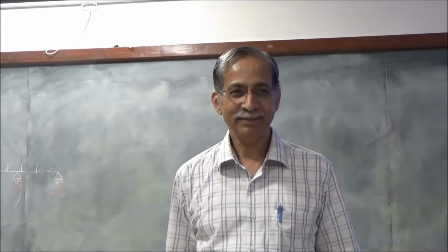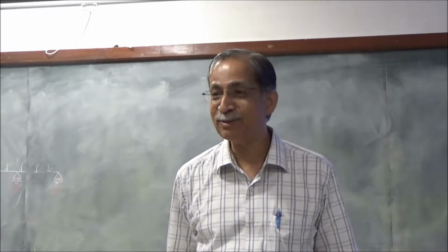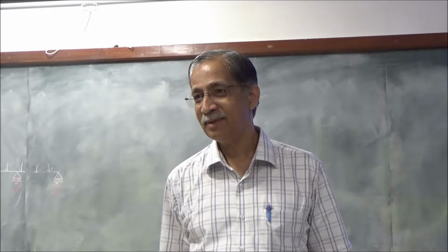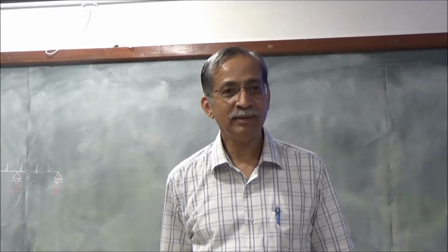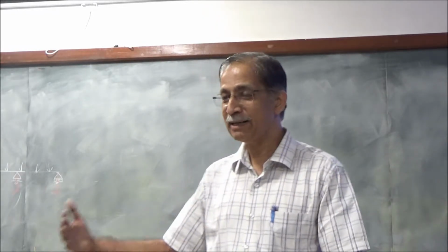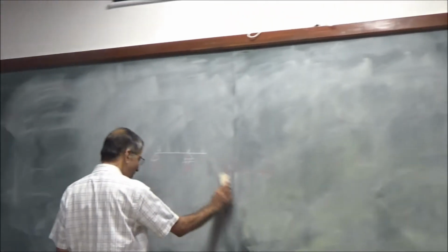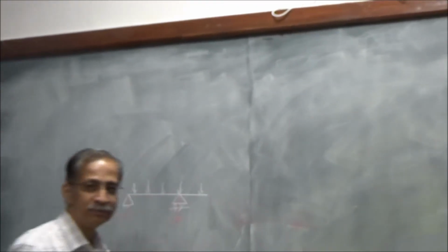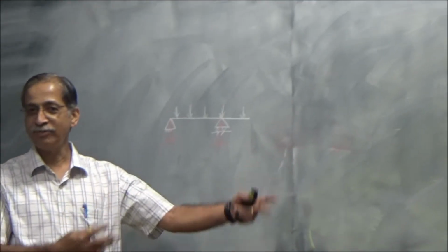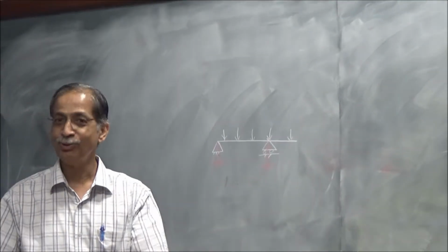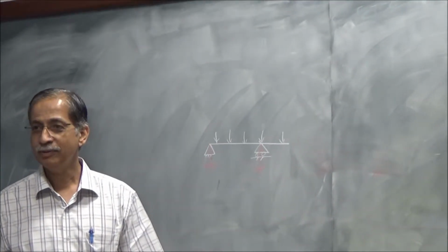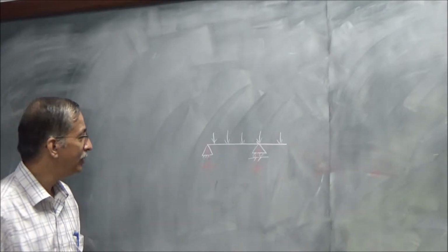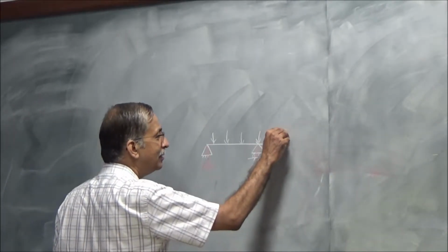Any method. First of all, can we take advantage of symmetry? If the loading is symmetric, we'll take advantage of symmetry. Half the job is simplified. And cut it here. What's the boundary condition I should put here? I'm sorry we've gone off the topic, but you should know all this. What should you do? Fixed. My God. Who's fixing it? I fix it.